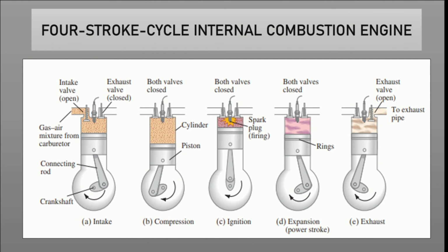The second one is the compression stroke. Here in the compression stroke, this stroke begins at the BDC, unlike the intake stroke which starts first with the TDC. It begins just at the end of the suction stroke, and it ends at the TDC. In this stroke, the piston compresses the air-fuel mixture in preparation for the next stroke, which is the ignition.